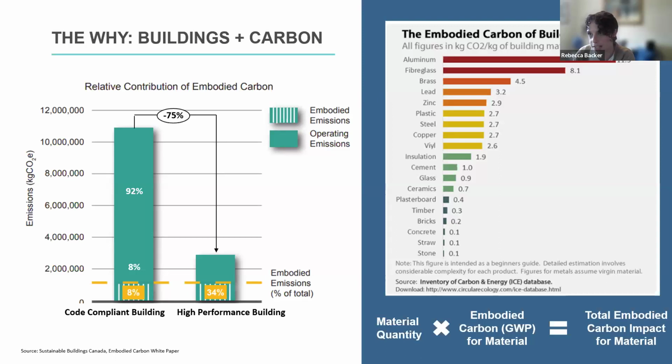If you don't have access to EPDs, or you're just starting to get into this world of thinking about embodied carbon from your building's perspective, a good rule of thumb is to assume that interiors like finishes and paints will have a lower environmental footprint relative to structural components like concrete and steel, with facade components like cladding and insulation falling somewhere in between the two.